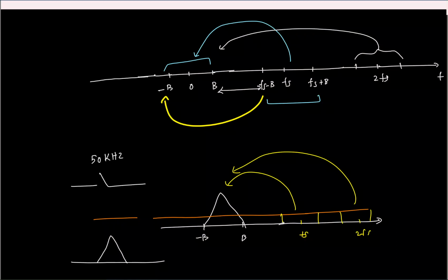So why will a 2Fs signal alias back into the band? Okay, so if I have a sinusoid at 2Fs, if I sample it at Fs, where will it alias back to? Yeah. If you are confused, you can always do this, right? Cos 2 pi... This is the signal. I am sampling it at Fs. Where is it getting aliased back to? DC, right? Whatever happens at Fs, Fs is not some pure number, right? Multiples of Fs also have the same property. When you're sampling this, it will happen at Fs also, 2Fs also, right? Yeah. That will also alias.